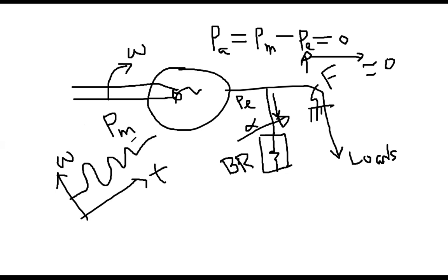So on one hand, the oscillation is going on. On the other hand, you are injecting power here. Every microsecond or millisecond, you are controlling this alpha. Consequently, it provides different power. Accordingly, this number is continuously changing, plus minus. That is causing some vibration on the shaft system.